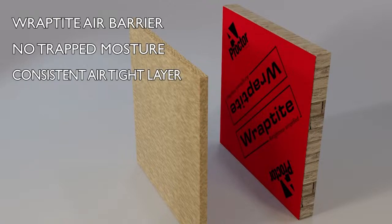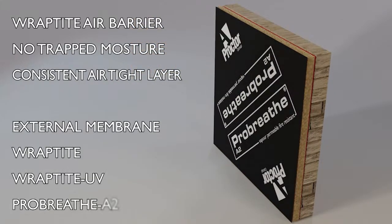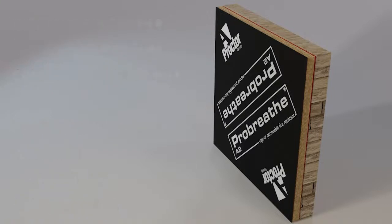Even where the existing fabric is airtight to a reasonable degree, a dedicated air barrier membrane can deliver more durable and consistent air barrier performance. What is being used is the external finish and the building type. An additional external membrane may also be used, which could be a further layer of Airtight, Airtight UV if open joint cladding is used, or ProBreathe A2 if fire performance is a particular concern.